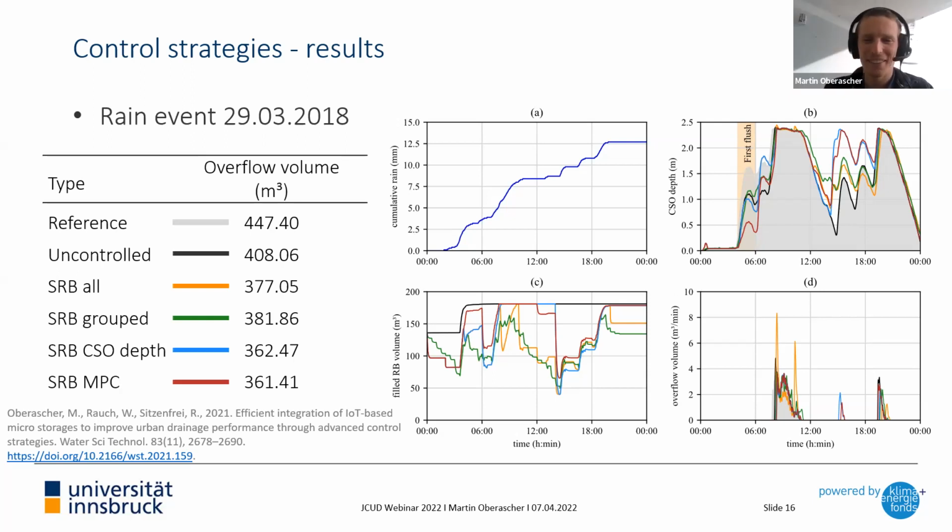Yes, but it's two different objectives. First, for the CSO, it would be beneficial when the storage volumes are always empty, and for the rainwater harvesting, it would be good when the storage volume would be always fully filled. Because with the weather forecasts, we empty the rain barrels before the precipitation events, and because of the errors, the rain barrels are not fully filled at the end, and then we decrease the rainwater harvesting performance. So it makes sense.